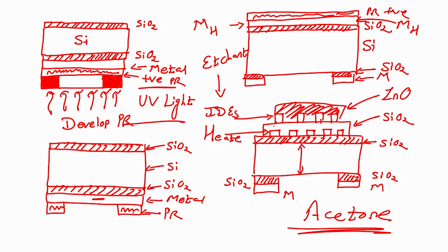So, you have to reduce the size of silicon. So, for that you have to etch the wafer, and when you dip this wafer, you can do two things. One is called dry etching, we will see, another is called wet etching. If you use dry etching, then you can etch the wafer by protecting the front area.